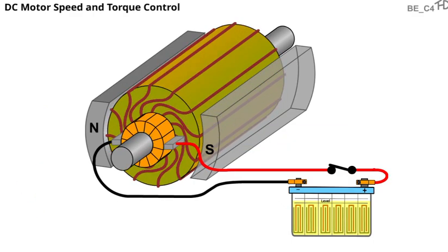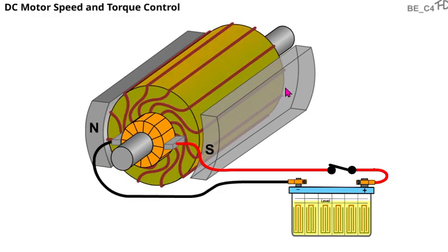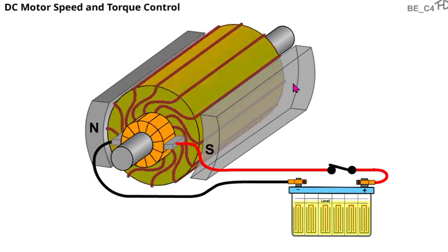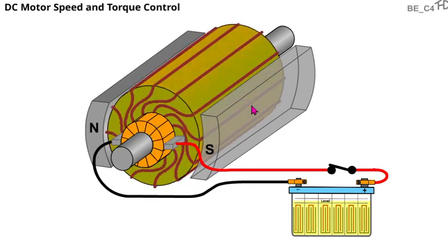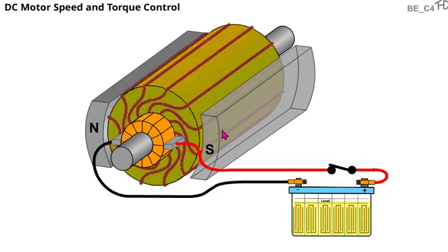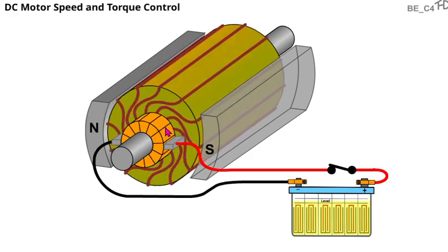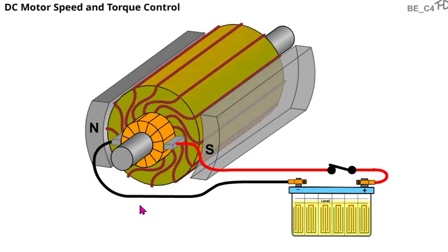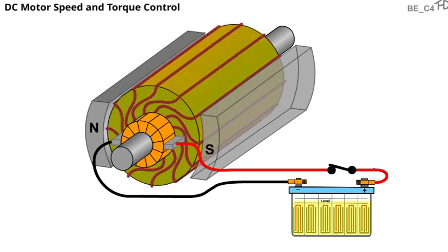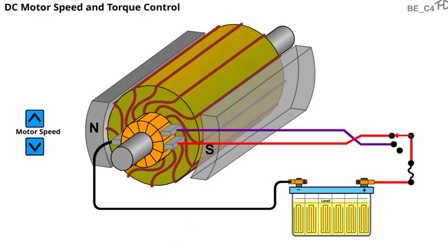First motor type we'll look at here is a permanent magnet motor in the field. Oftentimes these are called field coils. In this case, they're a permanent magnet. So they're constantly creating a magnetic field, and when we supply power through these coils, through the armature, we create another magnetic field. They interact with one another, and that causes our rotation.